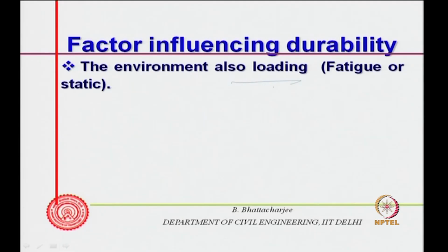We discussed this earlier a little bit, but fatigue loading will cause cracks earlier than static loading. So, environment is important, loading is also important. Where your loading is fatigue, you better take more care of durability. The crack can come at the surface, in the cover concrete, and therefore one has to be more careful about this. The cover is very, very important.